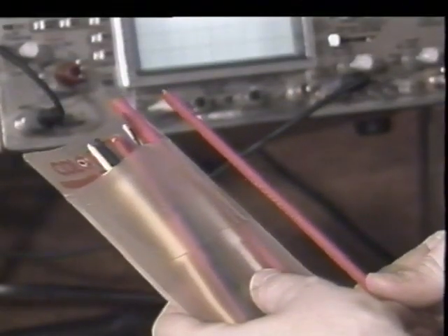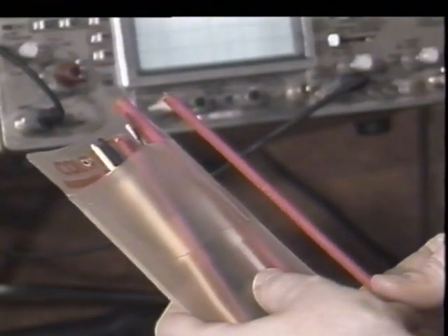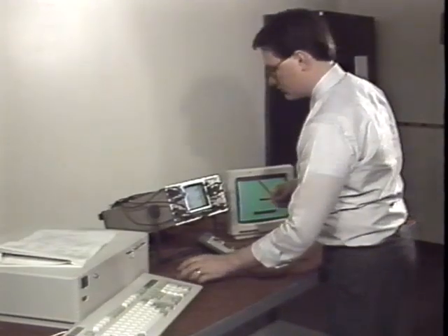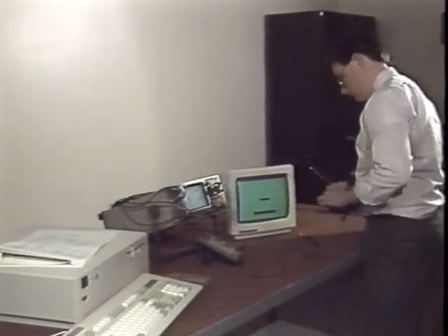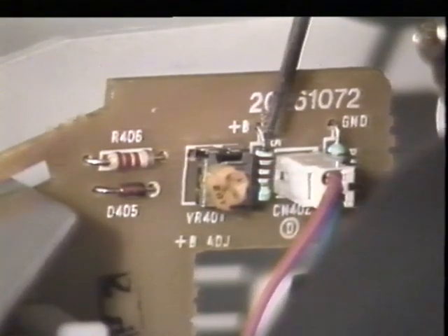Once the meter reading is stable, use a non-metallic alignment tool to bring the voltage into the specified range. In this case, the plastic tool serves two purposes. One is that it prevents adding capacitance to the circuit being adjusted, which can distort circuit output. In the monitor environment, it also protects you from shock if you accidentally drag the alignment tool across a high voltage point.